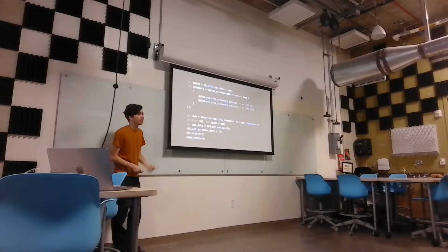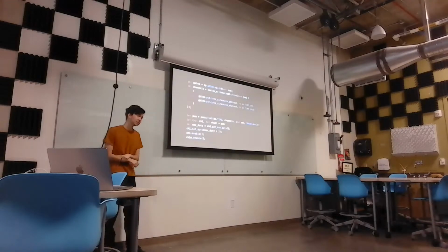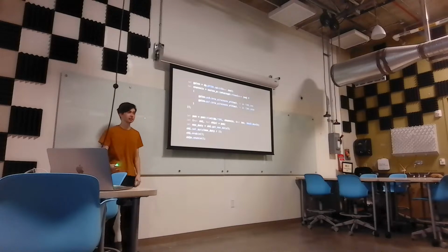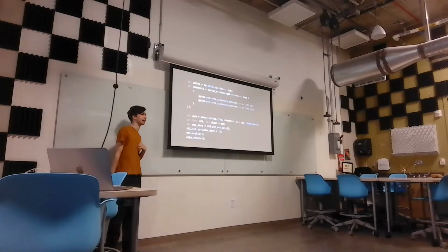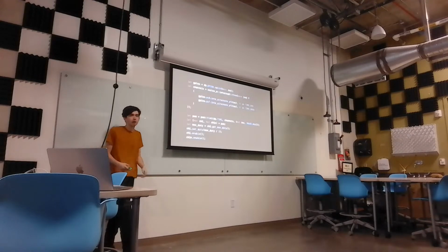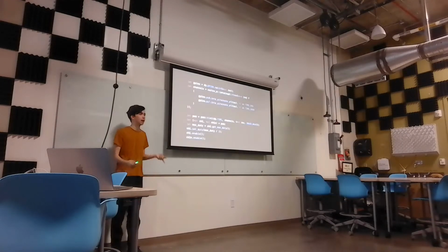Here's the thing though. That sucked. Did you see that? That was like 100 lines of code for PWM. It shouldn't be like that. And so above PACs, peripheral access crates, we use something called a HAL, a hardware abstraction layer. People don't want to be manually putting bits into memory. They should be able to just say, I want to make a PWM on these two pins, or I want to make an output on this pin, just like you do in Arduino, right?